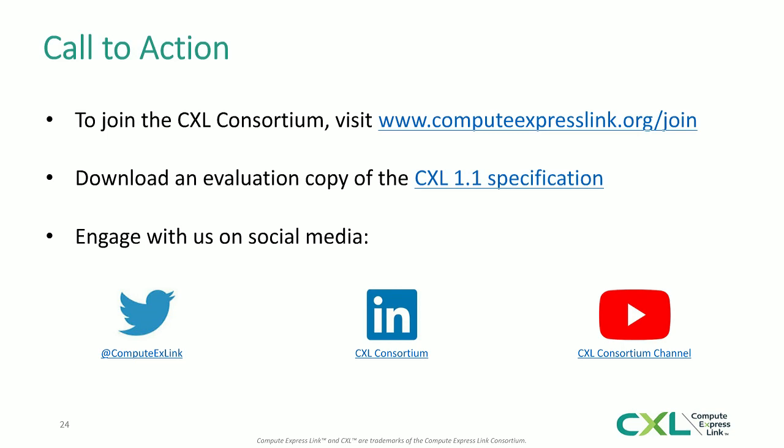Is there any difference of meta value meaning between Type 2 and Type 3 devices? No, the CXL.mem commands are the same. Whether it's a Type 2 or Type 3 device, it's just a different implementation, and in some cases a different response if necessary.